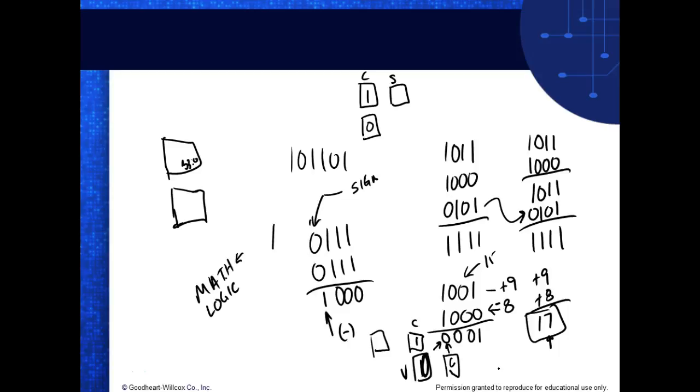You understand? So what do the flags do? Well, the flags, all they do is they come in here and they're looking at the results of the operation, not the two operands. They're looking at the answer, right? Y'all understand? And they're going to set or clear depending on the answer. It's up to the programmer to decide what to do with these flags.